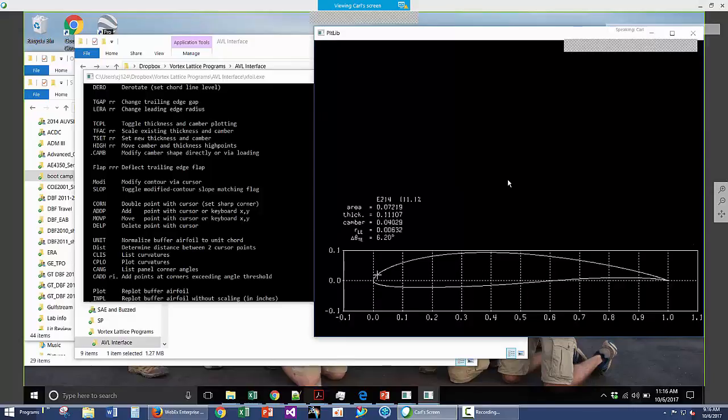If you have a low leading edge radius, what can happen is stall can occur very suddenly from the nose of your airfoil. And that goes to when you're building them as well. When you physically have your built wing, and if you're looking at it from a 2D type of viewpoint, like what does my wing look like?